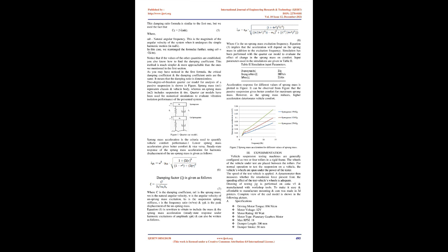9. Damping ratio. The damping ratio helps us establish which case of the damped motion we are considering. The table presented below will assist you in interpreting the results obtained from the damping ratio test. Note that the damping factor can't be negative. Table I, damping table. There are 3 useful formulae used in our damping ratio calculator. We will present each of them with an explanation below. (3) Where c is the damping coefficient, in Ns/m, and Cc is the critical damping coefficient, in Ns/m. This is the most basic formula.